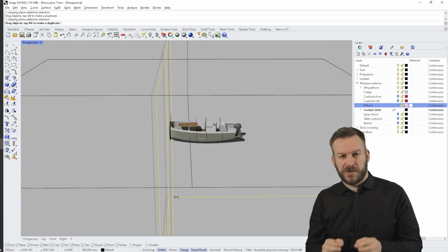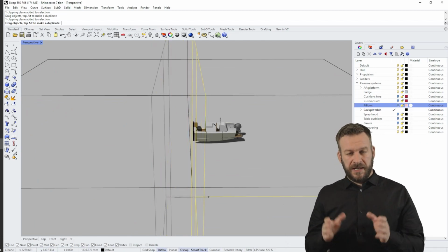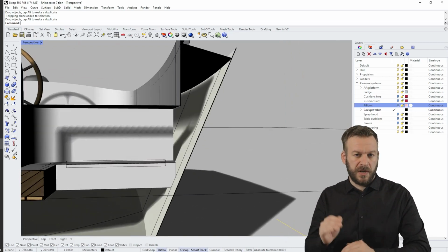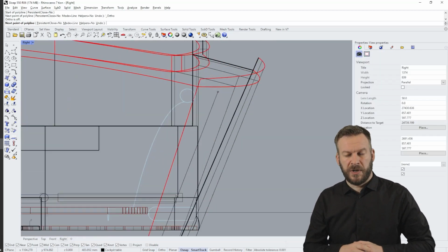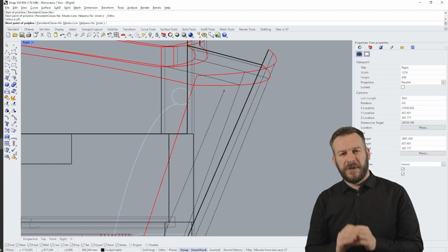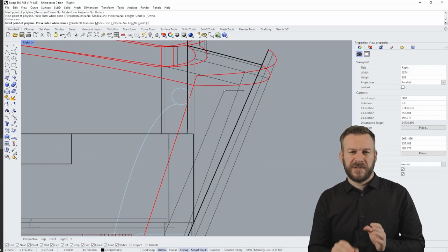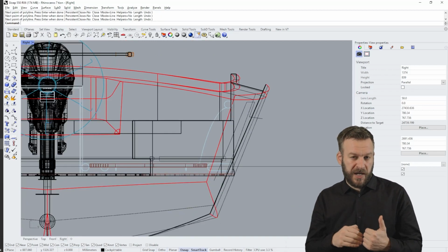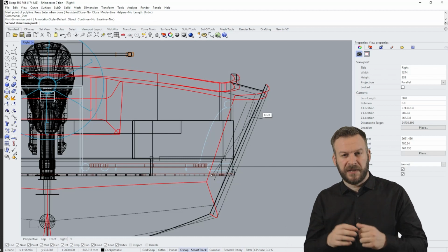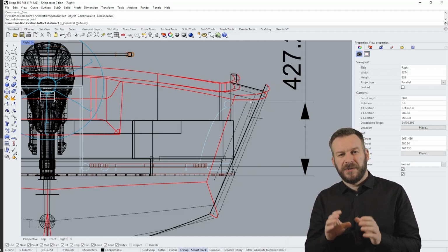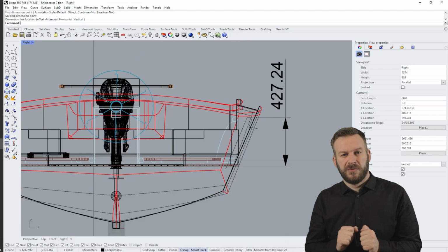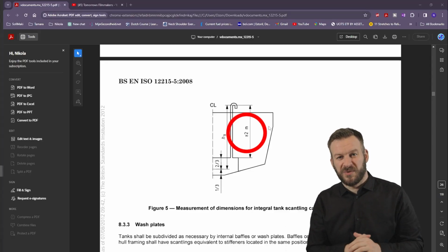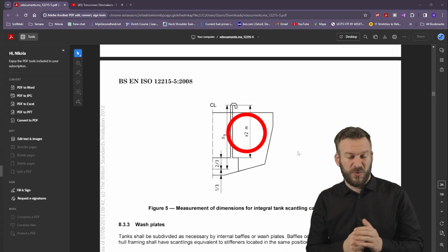Now let's calculate pressure for the tank bulkhead. They're very close and not that different in dimensions, so I will calculate just for one, and we can apply that to second one as well. So with tank bulkhead it's a different story. Every tank should be outfitted with the aeration point to release pressure or let air in to prevent vacuum in the tank and prevent implosion. So I will take a height of the aeration point just below deck, but as you can see in the rules, minimal height of the aeration point above tank top is 2 meters.